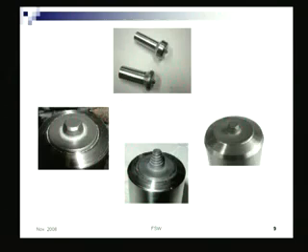Like a single welding torch can weld a plate of 5 millimeter as well as a plate of 50 millimeter. It depends on how many runs you go on depositing. But here a tool for 10 millimeter will not be suitable for welding a 12 millimeter plate or an 8 millimeter plate. For every thickness of plate, you will have to have a tool for that, because of the nib dimension.